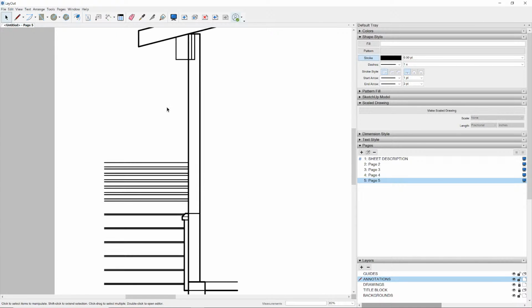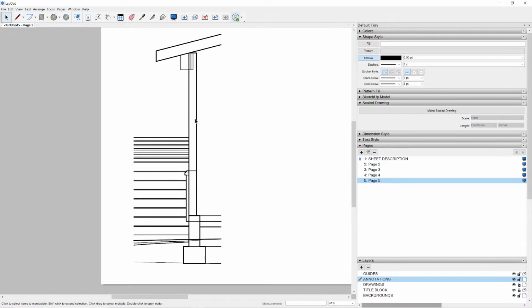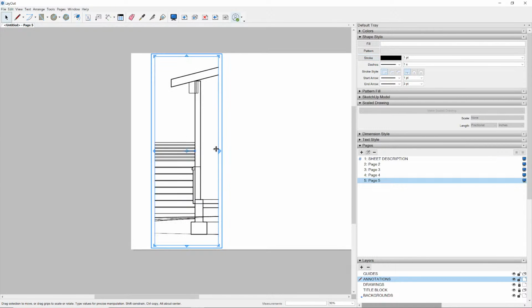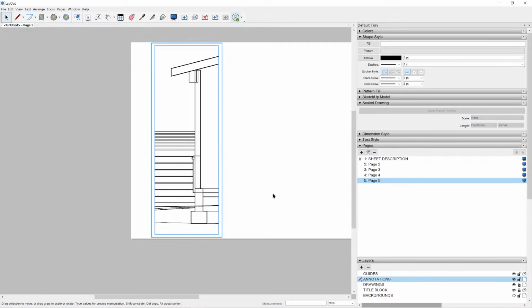Another way to do it, which is actually usually how I work, you can even do both, to be honest. You could leave this intact, copy it, and then paste it to the current layer, and then turn off the backgrounds. All right, so now you've got this drawing sitting here. I'm going to ungroup it, and then I'm going to right click on it again, and this whole drawing stack is just one viewport.